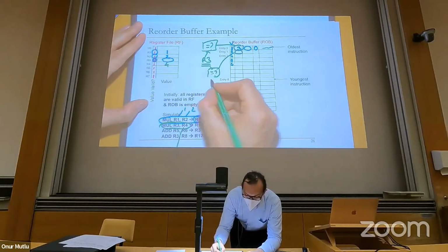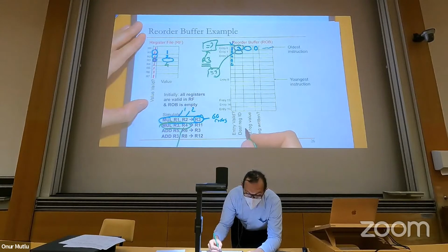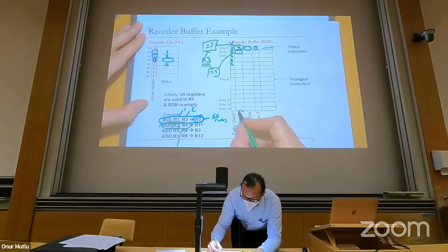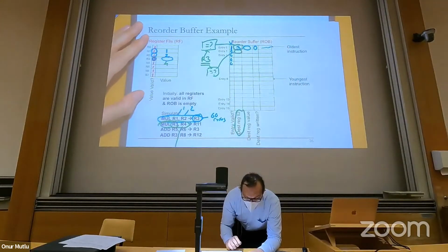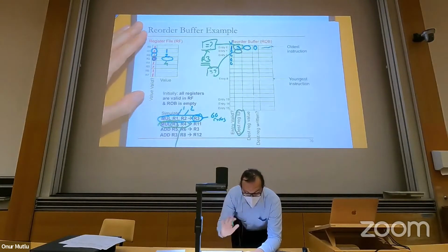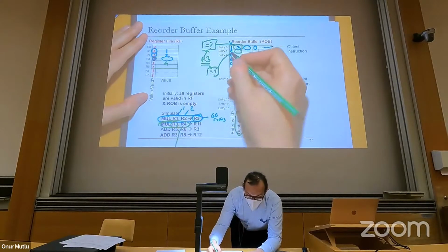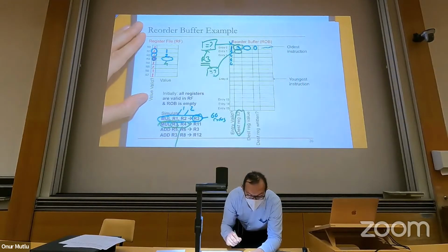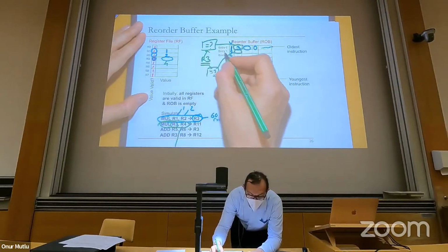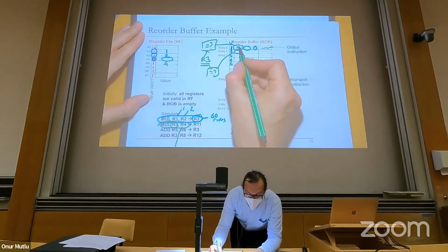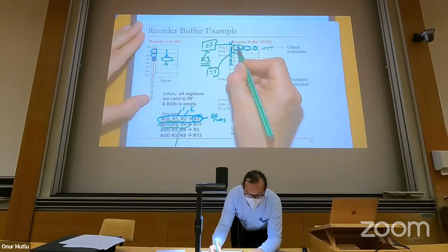So basically, I have comparators, 16 comparators in this particular case, that check whether this input R3 source register is equal to the destination register ID in the reorder buffer entry. And if it's equal, that could potentially supply the value. But that's not enough, because you need to consider only the instructions that are prior to you, meaning the valid ones, right? So you need to search the reorder buffer, find R3, and also check the valid bit. And you also need to find the closest instruction to you that writes to R3.